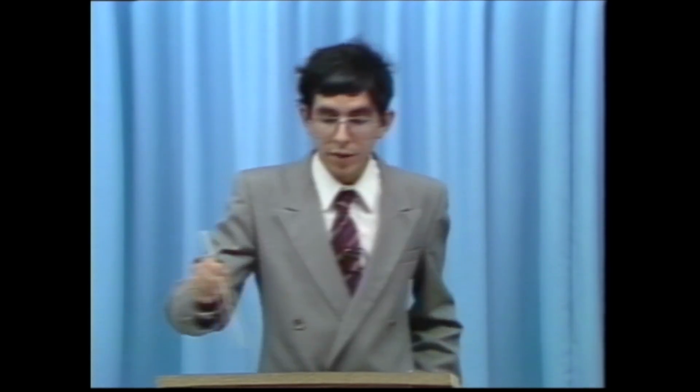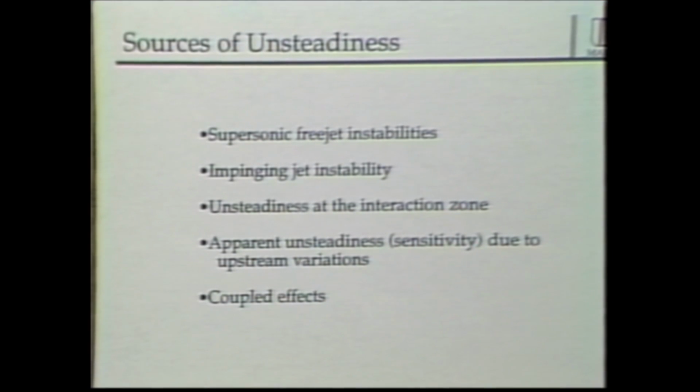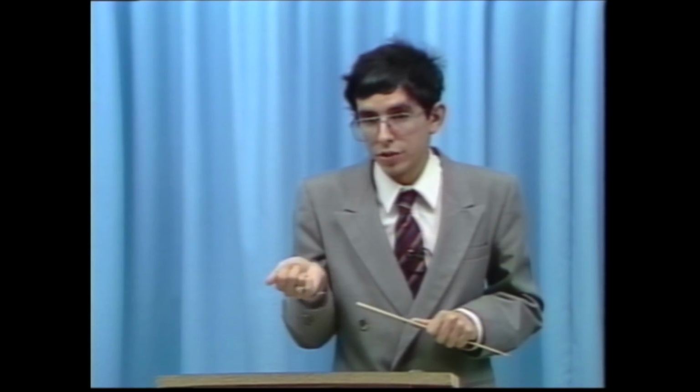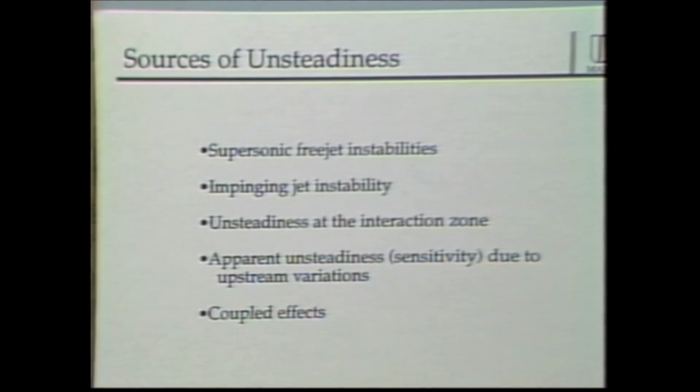Okay, one of the ominous aspects of that interaction, by the way, is it seems to be unsteady. Wind tunnel measurements have shown that it bounces around. There's been some computational work that also shows that it bounces around. So you can imagine, not only do you have this free jet pointed at your cowl, but it's a free jet that you don't even know where it will be located on your cowl. So it's also a design condition. And even if you design your bow shock system so that that jet isn't pointed at your cowl, because it's unsteady, you might very likely have a situation when a free jet appears when you don't expect it. And that's another advertisement for a research area that deserves more investigation.